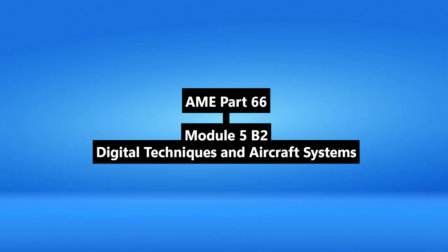And because 8 and 16 are powers of 2, converting is easy, you just group the binary digits. 3's for octal, 4's for hex. Okay, so it's like a shorthand, makes it easier for humans to read and work with. Pretty much. A massive convenience for programmers, engineers, technicians, reading documentation. It just makes handling the underlying binary much less painful.